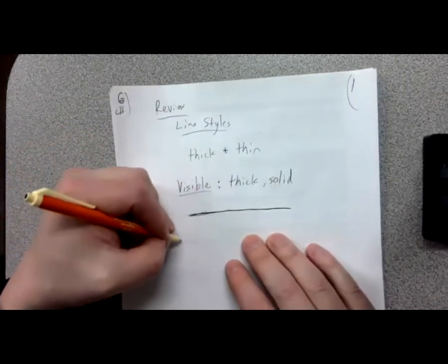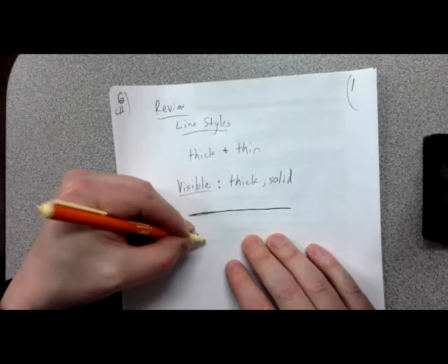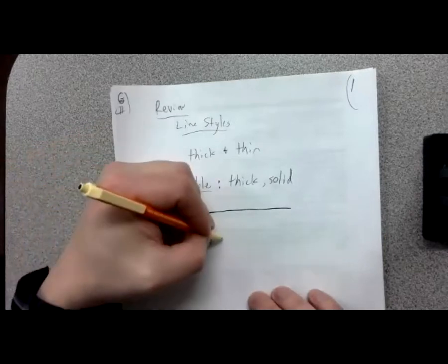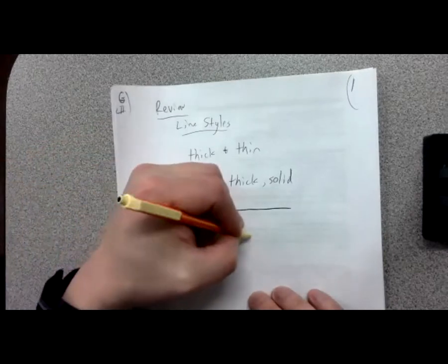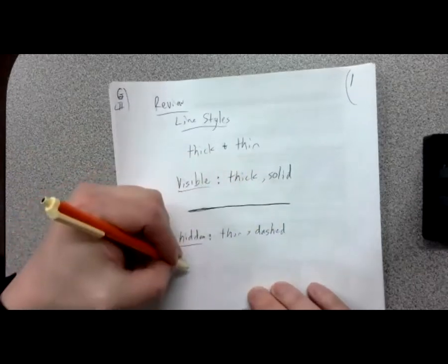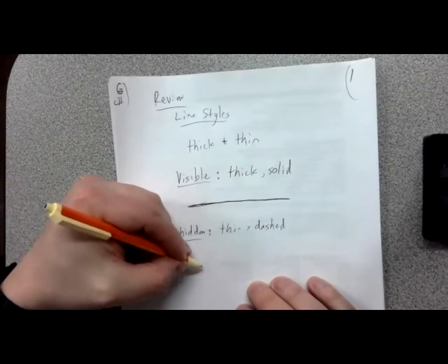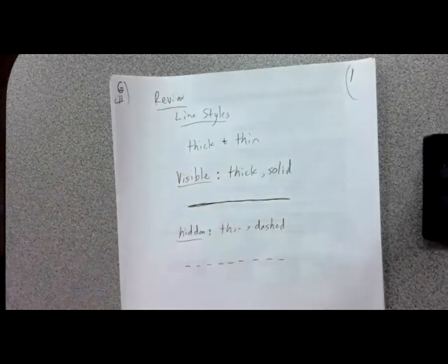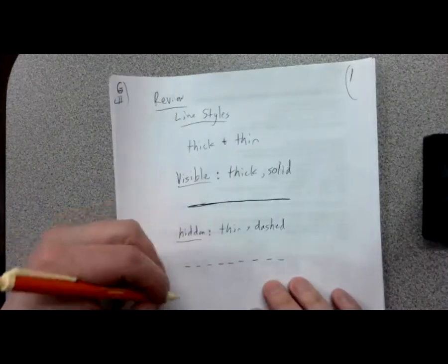We talked about several line types. Let's talk about the main ones. Three that are kind of bread and butter, especially the first 2 here, are real bread and butter. The hidden line type, those are thin and they are dashed. And it's just a short dash that repeats. And again, for me, if I'm just using a pen or pencil, the easiest way to ensure thin versus thick lines is to just simply do multiple passes with thick lines, single pass as best possible, a single pass for the lines that are supposed to be thin. And with pen or pencil, that normally gets you pretty close.